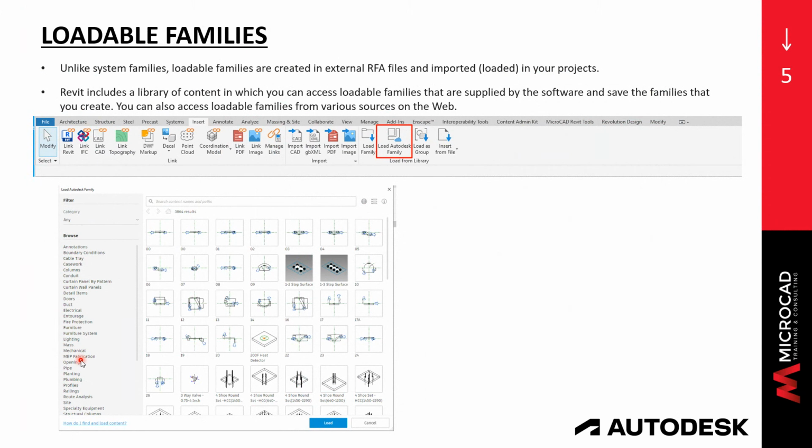And this is where you find all the families that you get from Revit out of the box. I advise everybody, before going and acquiring families on the web all over the place, investigate this library. Make this library your own. It's like when you were little and they would give you this box of colors. Try them out, check them out, and if you need to create your own family, for me, the starting point should be any of these families that you get from Revit out of the box, and then develop from there. Why? Because these families are proved and tested. They work. We know they work. So with little variations, you can make them your own.